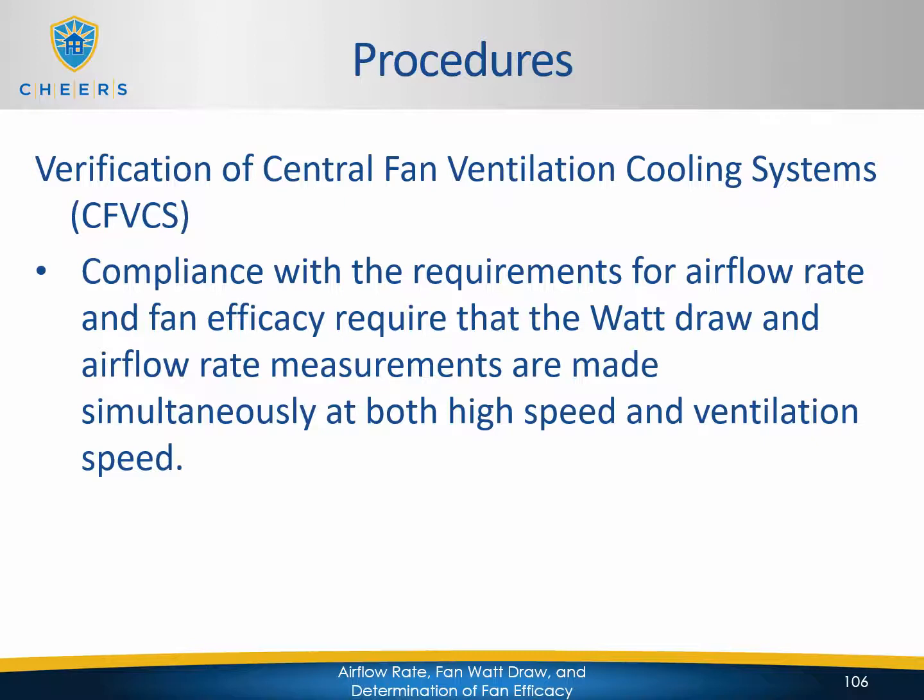Now this is performance only, so you're not going to have any prescriptive requirements on this. You're going to look at that performance CF1R, define what the target is, and you're going to measure it using the same methods as what we used for verifying just the regular airflow and fan watt draw. You're going to do the same thing, but now you're going to be doing it in ventilation speed.